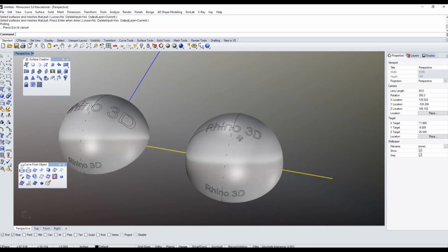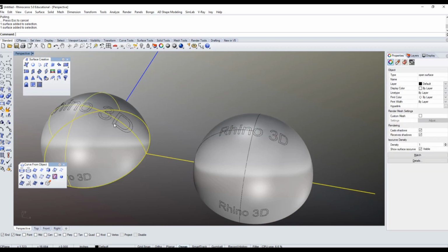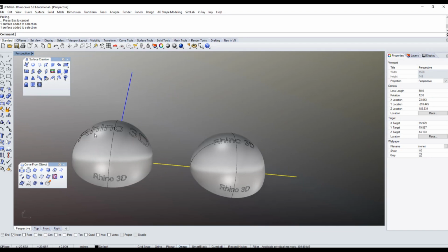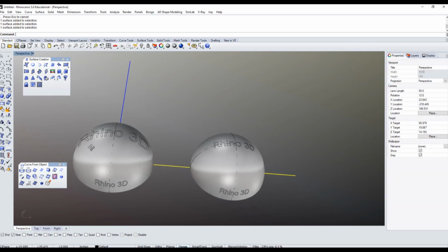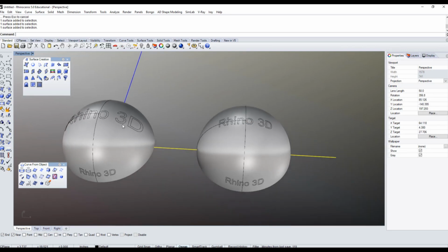And pull curve is also very important. It's a tool that I would use quite often. You see less deformation when it's projecting this curve into that surface versus this one. Like I told you before, in the first case with project curve, it just projected as if it was a sort of extrusion, and it found the intersection between my extrusion and my surface here, and it gave you this resultant. So that's why you see stretching going on.